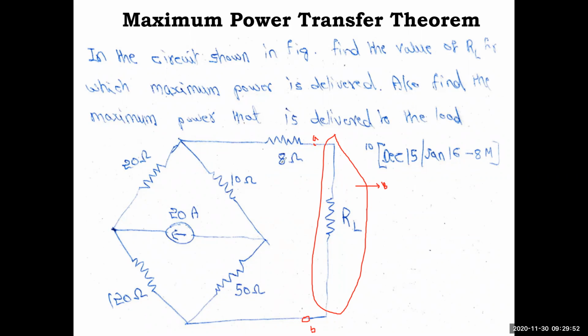You know Thevenin's theorem. So apply Thevenin's theorem and find the Thevenin's equivalent voltage and resistance, that is the Thevenin's equivalent circuit, VTH and RTH, for this circuit. Once that is done, you can easily find RL equal to RTH and then use the formula power is equal to IL square into RL. Using that we'll calculate. Very simple, so let's proceed.